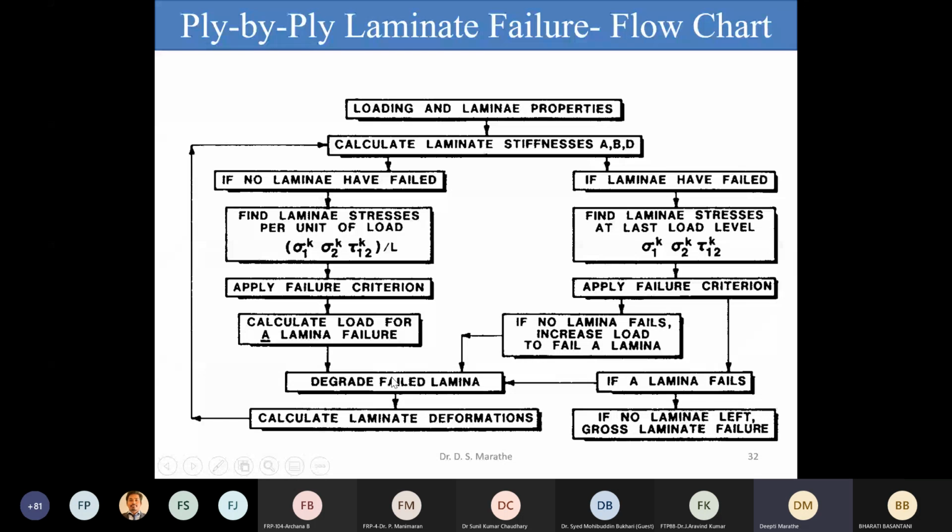So basically, I have built my laminate taking into consideration my application. Therefore, I have laminas at certain orientations placed there. I'm also aware of the loading conditions, and therefore I have designed it to be, say, a completely symmetric laminate or anti-symmetric laminate depending on my requirement. And then this algorithm has been analytically calculated or simulated, and then the experiment is actually carried out for testing of this particular laminate.